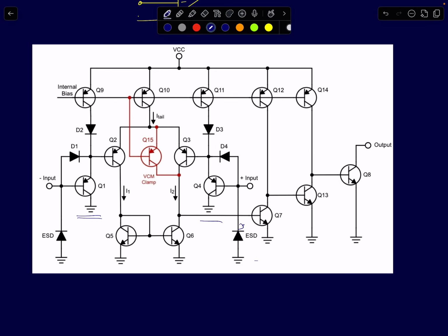Now when we were looking at the schematic of the 393 IC, we said the schematic made total sense because the first stage happened to be a very high gain PNP transistor based common emitter amplifier. It was a differential to single ended converter. Then we had a cascade of three-stage common emitter amplifiers. Okay, common emitter, a common emitter, and then a common emitter finally. Now, this made total sense except the first stage.